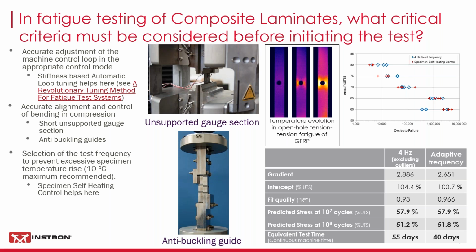Next thing to consider is the test frequency. Testing these polymeric materials, they will heat up at relatively low frequencies in areas of high stress and strain. And you can see that in the illustration there of an open hole specimen subject to cyclic loading. And you can see the heating around the hole there, in the infrared images. So one of the things that we've introduced recently, in the last few years, is specimen self-heating control.